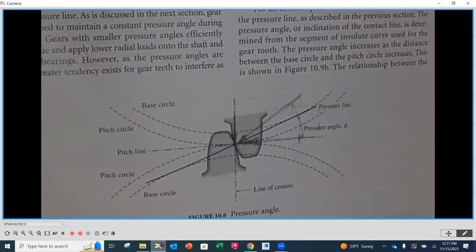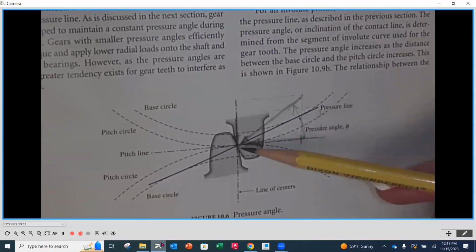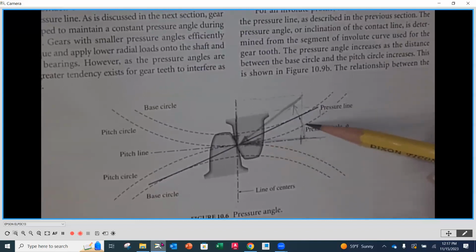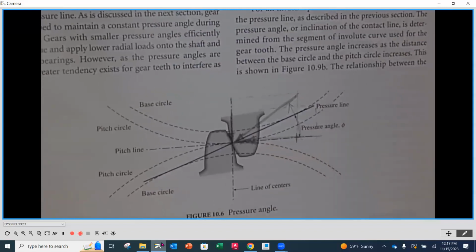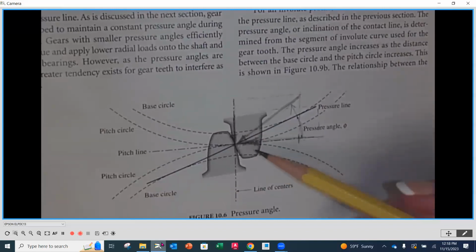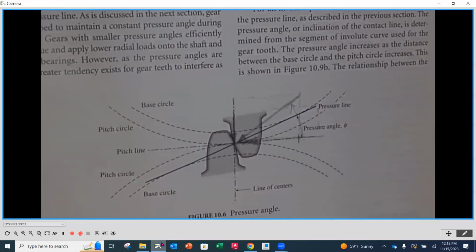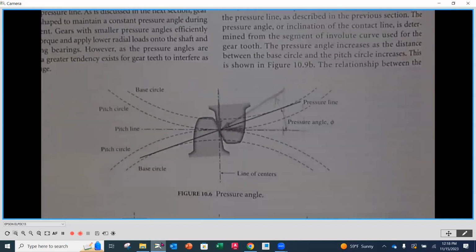Now, one more pressure angle. If we do 14.5, this gets more shallow, and we're doing that very same thing but in the opposite direction. At 14.5, we get a higher tangential and less on the radial. As you can imagine, you then have a higher potential of shearing teeth off sooner than later. So that's why 14.5s are not used anymore for new designs, only for replacement parts for existing machinery. Okay, so pressure angle. Any questions about that?